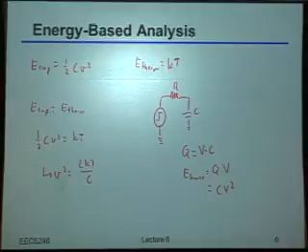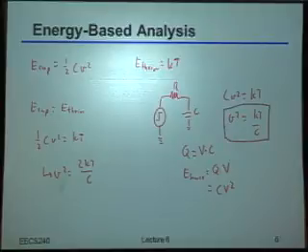So if you really track things that way, meaning it's not just the energy that's stored in the cap that matters, it's actually the energy that came out of the source, you would then indeed say that you just have CV squared is equal to kT. And so you'd get V squared is equal to kT over C, just like we expected. Okay? Does this make sense to everybody?